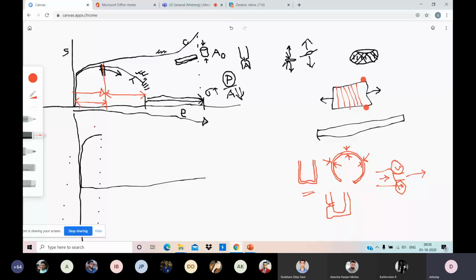And what ensures good uniform elongation? Strain hardening. What is your name? Sir, Jyoti Ranjan. Jyoti Ranjan, your answer is good. So strain hardening. Now Jyoti Ranjan, can you tell, how do you know that uniform elongation and strain hardening are related? Sir, we previously derived an expression that uniform elongation equals n in order to prevent necking. Very good. So that is the answer.